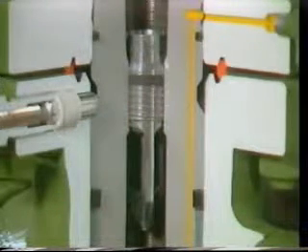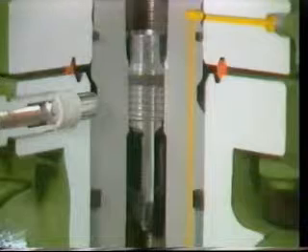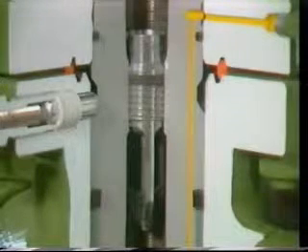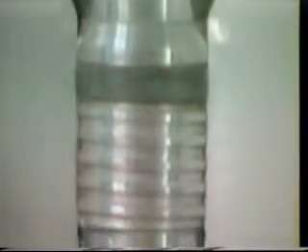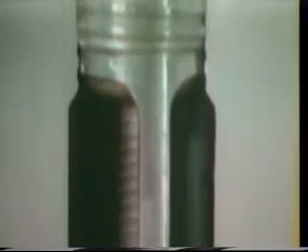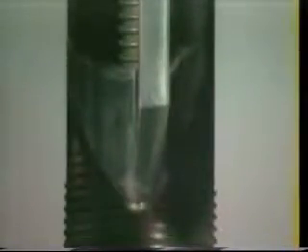Both the mandrel and split hanger types can be machined to accept back pressure valves and to utilize extended neck hangers to seal in the tubing head adapter. A back pressure valve is used to seal the tubing, while the blowout preventers and Christmas tree equipment are installed or removed. The back pressure valve can also allow fluid to be pumped down the tubing for functions such as displacing drilling fluid before connecting the tree to the tubing head.